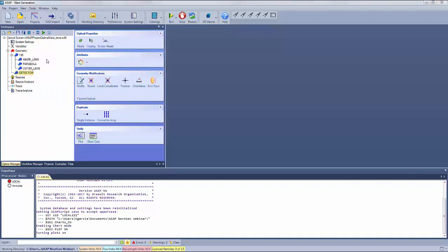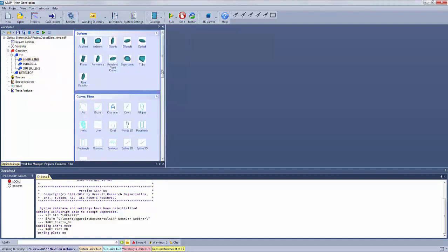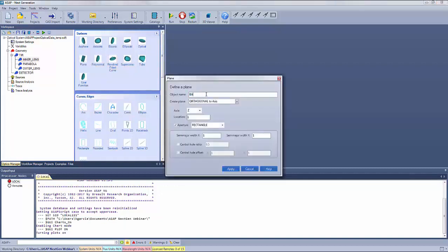Now we'll begin defining the actual geometry for these different components. Let's start with the inner lens. We're going to create a geometry component here, which is going to be the base. We'll create that out of a planar element. We'll call that base. We'll come down here and set its location at 0. It will have an elliptical aperture. And here we will use some of our variables which we previously defined. Base semi-diameter, diameter, and it'll have a central hole.